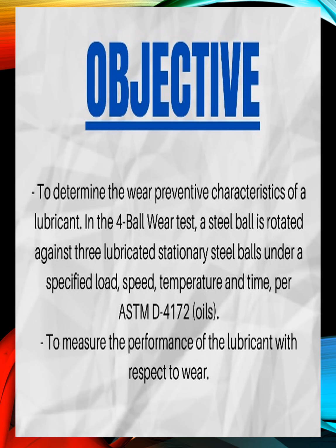ASTM D4172 is used to measure the wear scar diameter of the ball bearing as well as the COF of the lubricant. In this experiment, the test load is set to 40 ± 0.2 kg, while the temperature is maintained at 75 ± 2 degrees.